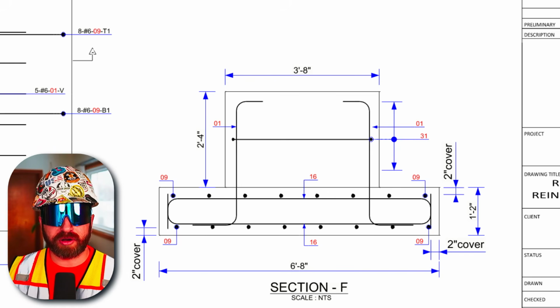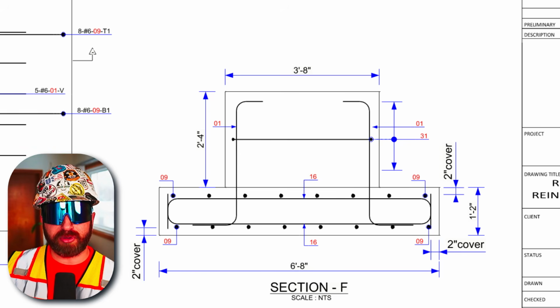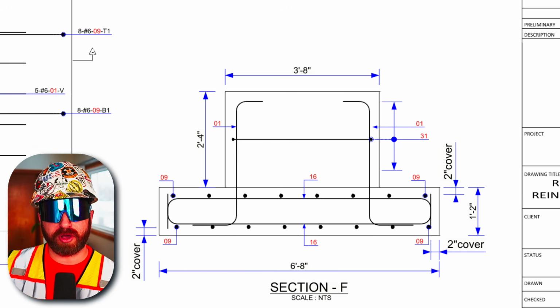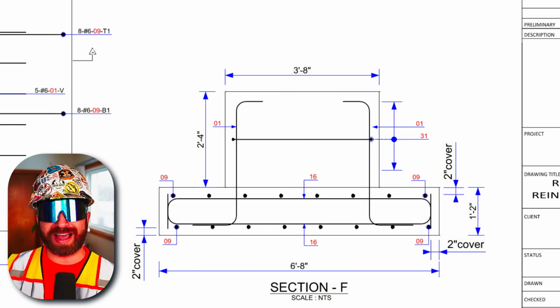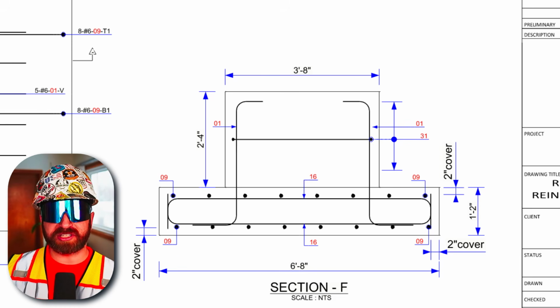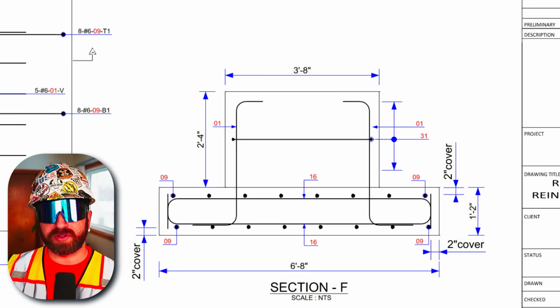So the final thing I'll note here is that there are also anchor bolts and embed plates, if you recall from my structural review video, supporting the structural steel above, which will need to get installed alongside the rebar prior to pouring concrete. Steel fabricators will put together their own set of shop drawings showing the placement of these that we would need to reference alongside these rebar shop drawings. Okay, that is our broad overview of reading and digesting rebar shop drawings. You should now be better equipped to understand your own set of rebar shop drawings on a project and how you come to get a set of rebar shop drawings.